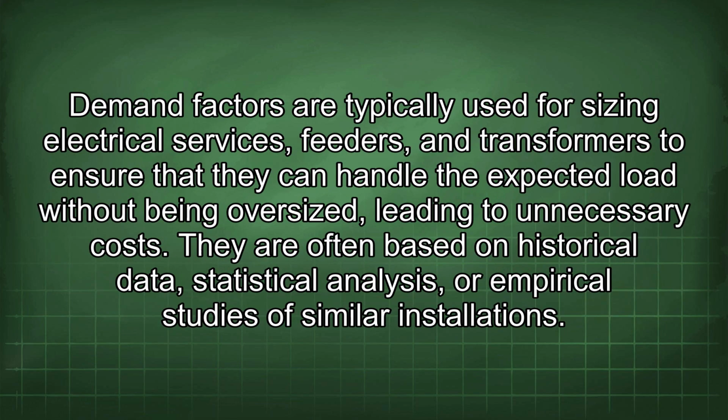Demand factors are typically used for sizing electrical services, feeders, and transformers to ensure that they can handle the expected load without being oversized, leading to unnecessary costs. They are often based on historical data, statistical analysis, or empirical studies of similar installations.